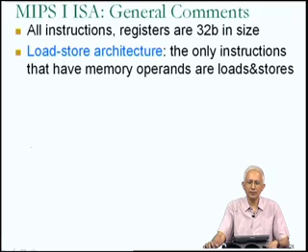Another characteristic of the MIPS1 instruction set is that while it is, as I had mentioned, a RISC instruction set, you may also see it described as a load-store instruction set or a load-store architecture. And it is given this name because the only instructions in this instruction set that take operands out of memory are the load and store instructions.